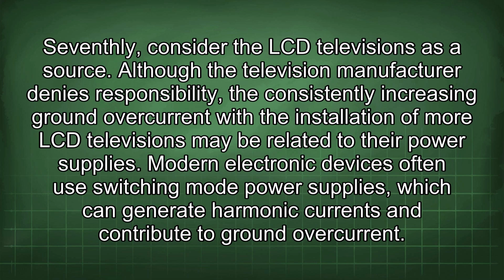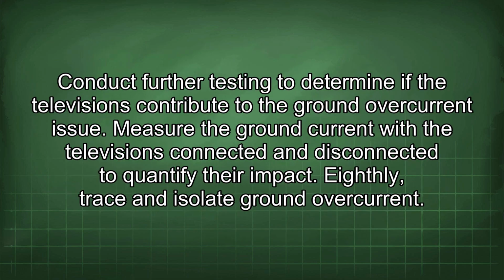Seventhly, consider the LCD televisions as a source. Although the television manufacturer denies responsibility, the consistently increasing ground overcurrent with the installation of more LCD televisions may be related to their power supplies. Modern electronic devices often use switching mode power supplies, which can generate harmonic currents and contribute to ground overcurrent. Conduct further testing to determine if the televisions contribute to the ground overcurrent issue. Measure the ground current with the televisions connected and disconnected to quantify their impact.